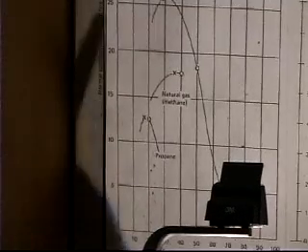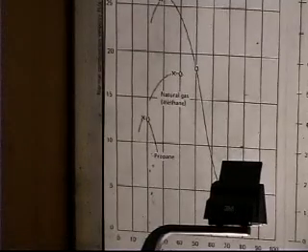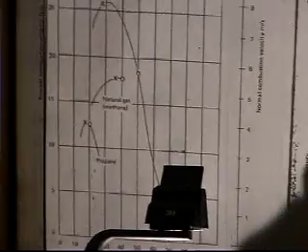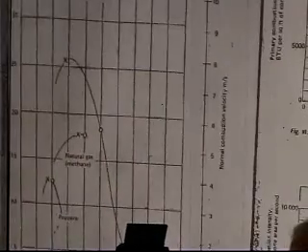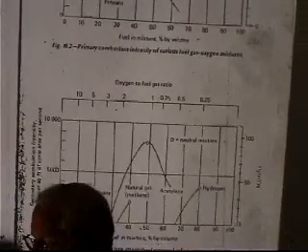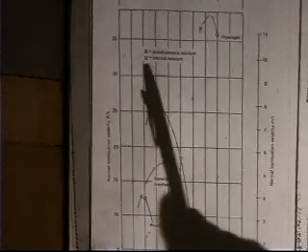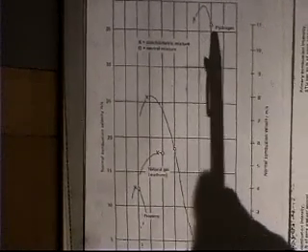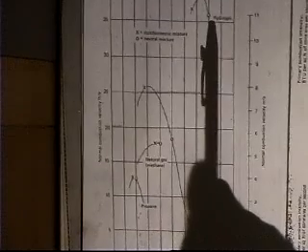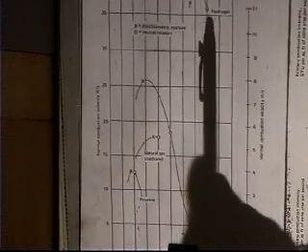This is actually the normal combustion velocity. This is primary combustion intensity in BTUs per square foot, which is only the welding journal would use English units like that. This is secondary combustion velocity. But in any case, the combustion velocities are going to peak somewhere. The X value is the stoichiometric mixture, and the circle is the neutral mixture, where there is no oxygen left over.